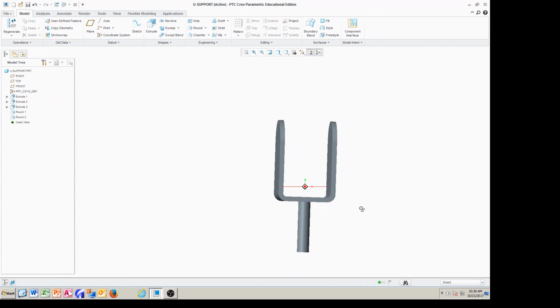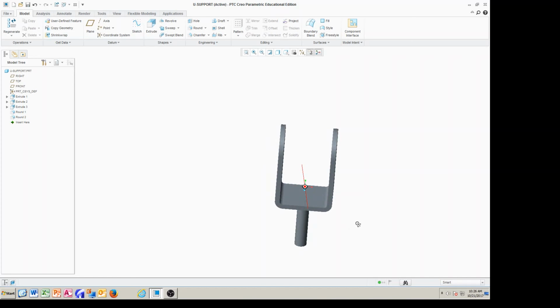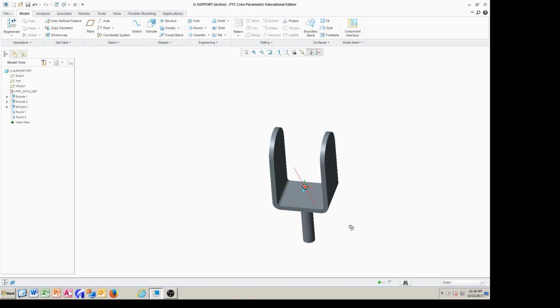Okay, in case this was used in cyclic loading or fluctuating loading, we don't want this to break, because if the failure is by fatigue, the number of cycles to failure should increase by adding the fillet radius.